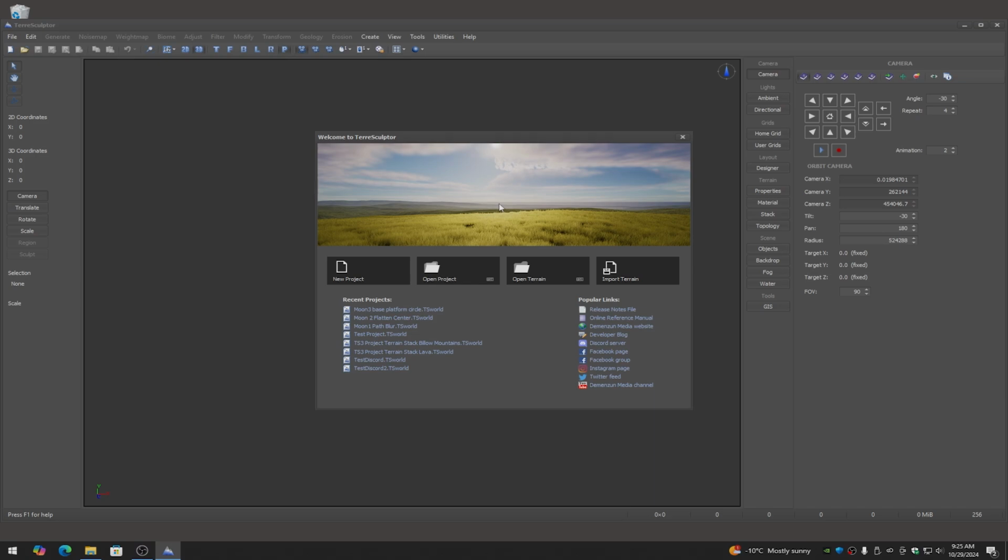So for example, if you're exporting out of Photoshop, Photoshop will use a 16-bit PNG for full scale of 0 to 65,535 without actually having any elevation data. All it knows is the grayscale values. And depending on the software that you're using, all that you may have is just the straight raw elevation data without any height or elevation range information in it. Only digital elevation models contain GIS information for height data.